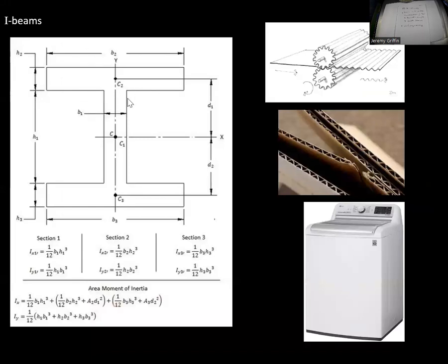Also, this I-beam, here's the I-beam again, cut away, has an associated moment of inertia, and you can calculate that. We did this, I think back in December, something similar to this, like the parallel axis theorem, the whole deal. And anything that has more moment of inertia has increased strength. An example of that could be corrugated cardboard. The material itself is really flimsy paper, right? Now, why not just use really flimsy paper? Well, that would create a really flimsy box. But if you corrugate it like this, now it can handle stresses in all different directions.